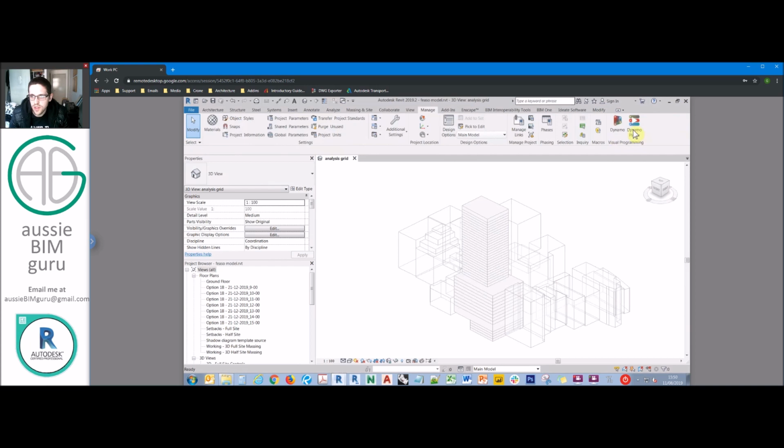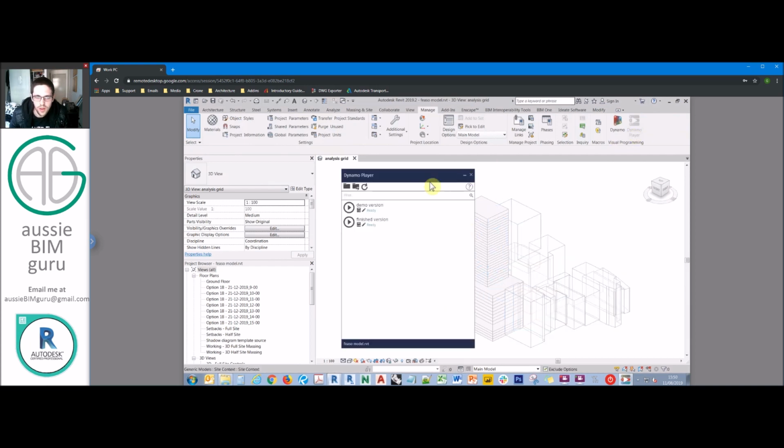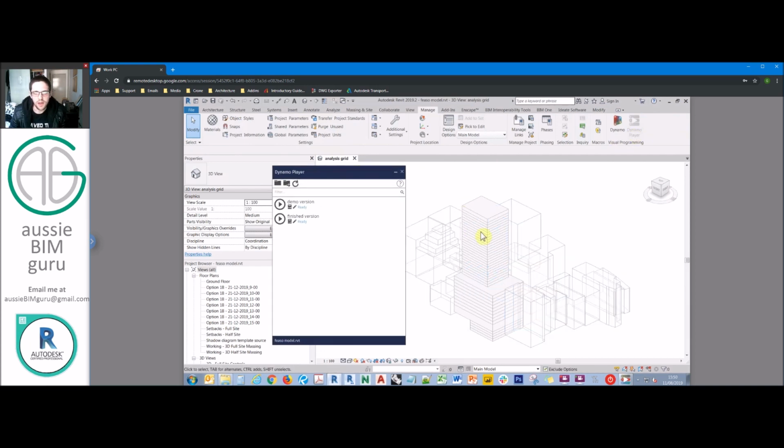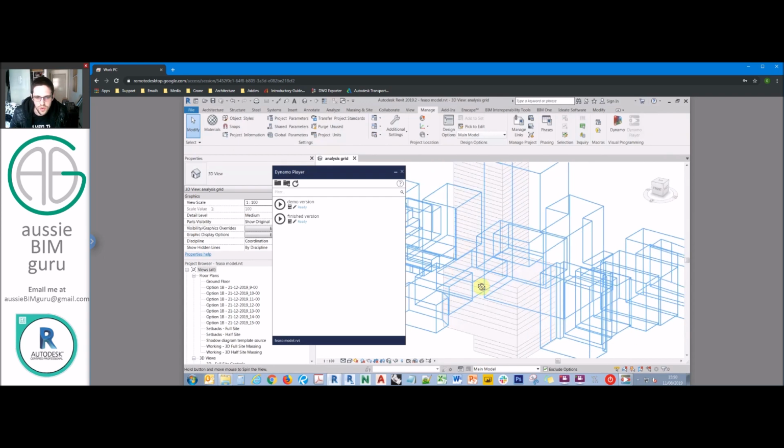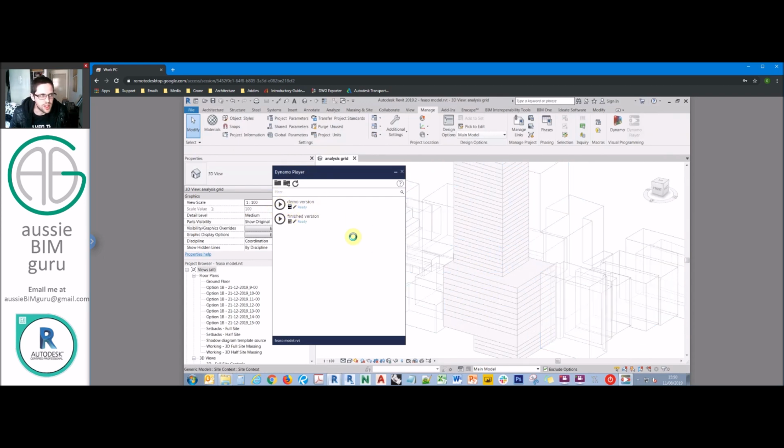and we'll set up some of those sensors. So the good thing about having UV spacing is I know that my commercial floor is 4 meters from floor to floor. So if I go into my inputs, we'll try and get our spacings to match that vertically so that we can sort of test on a level by level basis. You can obviously manually place these points as well. You don't need to use Dynamo. And we can obviously delete them too to reduce the number of samples if you know there's a zone that the script has put them in that you don't need to test.